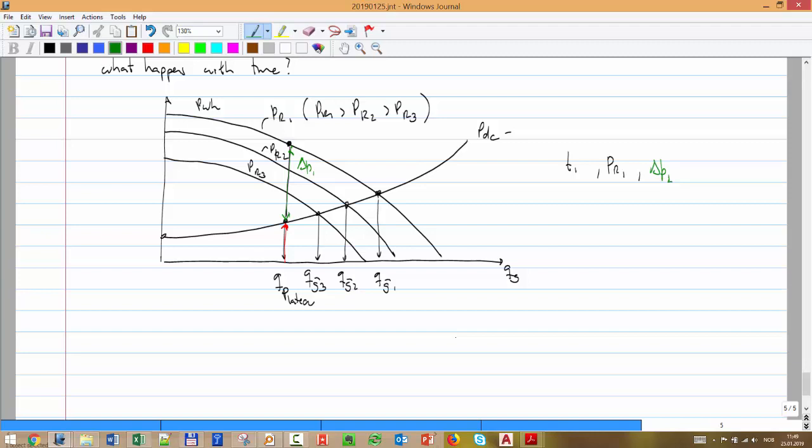And then you say, yes, I can produce plateau rate, no problem, let's go to the next time step. Okay, you assume constant, you go to time 2, you calculate NP2, or in this case GP, cumulative gas production, and then you calculate PR2. Then you calculate this curve. And now you want to verify, am I still able to produce in plateau mode?